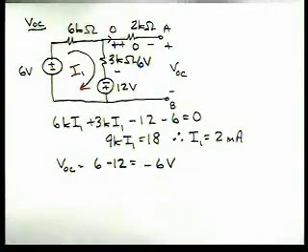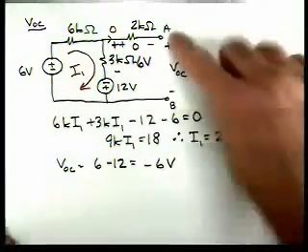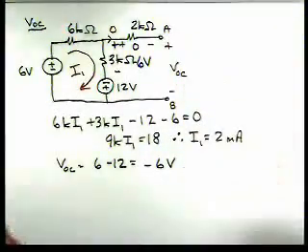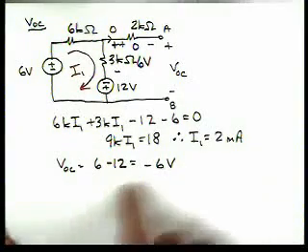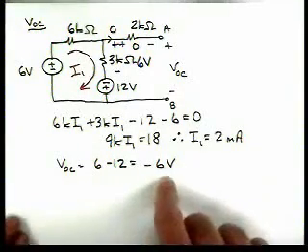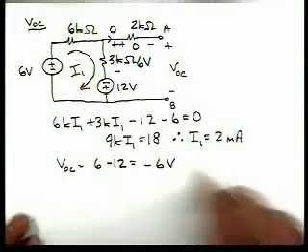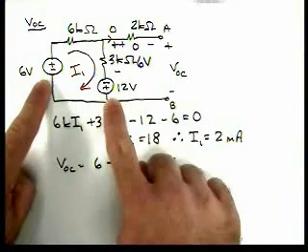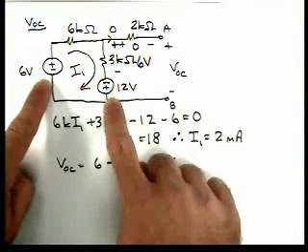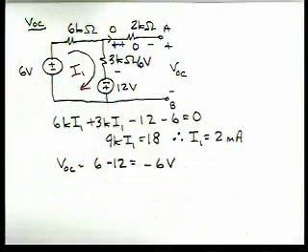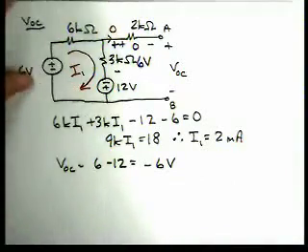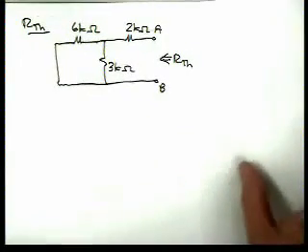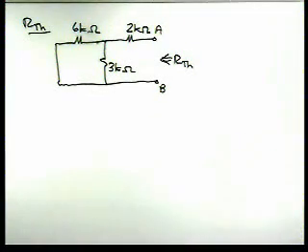So we remove the 4 kilo ohm resistor. We found the voltage at the terminals A and B. We found the open circuit voltage. Now we're going to find the Thevenin resistance. For that, we're going to take this circuit and turn these two voltage sources to 0. So we're going to turn this one to 0, this one to 0, and really 0 volts is characteristic of a short circuit. So when we do that, here's our circuit for finding the Thevenin resistance.